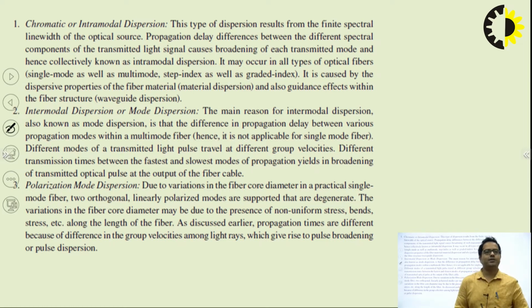In the case of intramodal dispersion, this is basically the result of the finite spectral width of the optical source. We have an optical source, it could be a laser, or it could be an LED. Whenever we launch light inside the optical fiber, and the spectral line width of the optical source affects the spreading of a pulse, that is known as intramodal dispersion. So intramodal dispersion is basically due to the finite line width of the optical source.